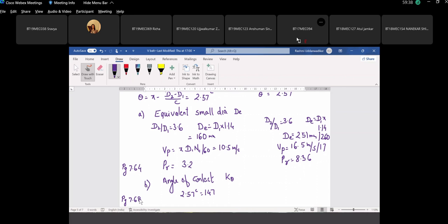So you see for V-belt and for 180 degrees, the correction factor is 1. As the angle theta decreases, the correction factor value decreases, and this will be multiplied to the rated power, and so the actual power transmission capacity will also go down. For 148 it is 0.92, for 145 it is 0.91. So we can safely go with 148, which is 0.92. So for both the cross sections, we are using K theta as 0.92.